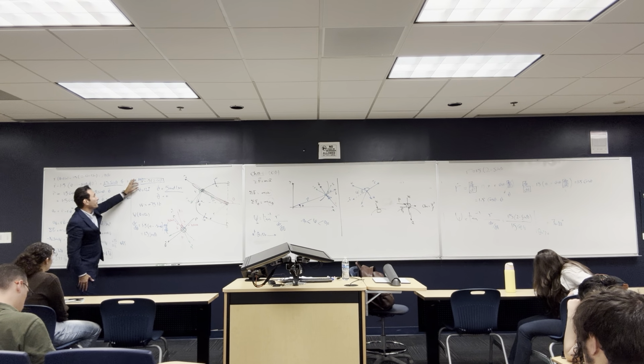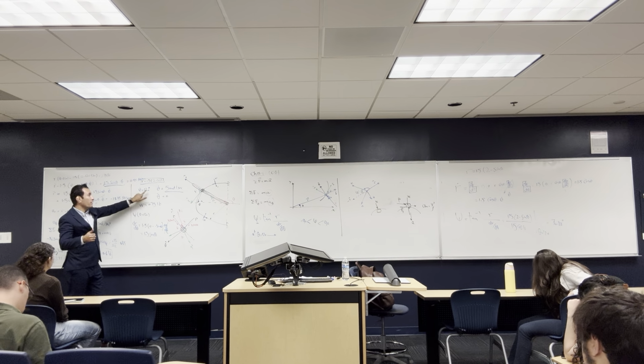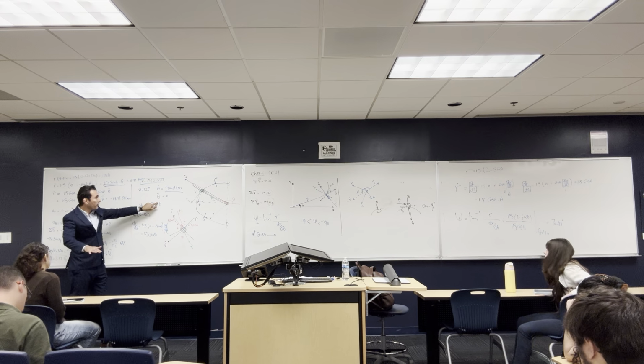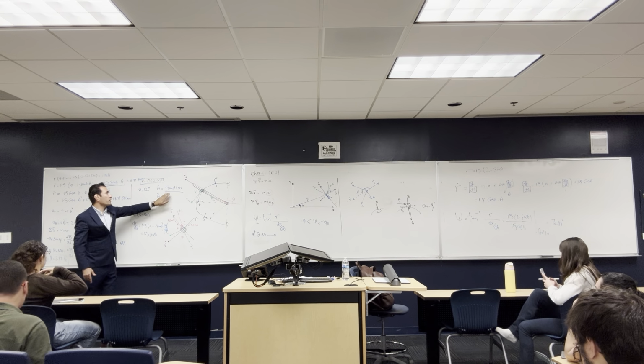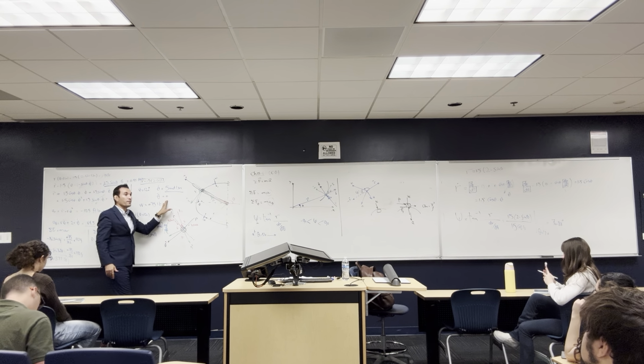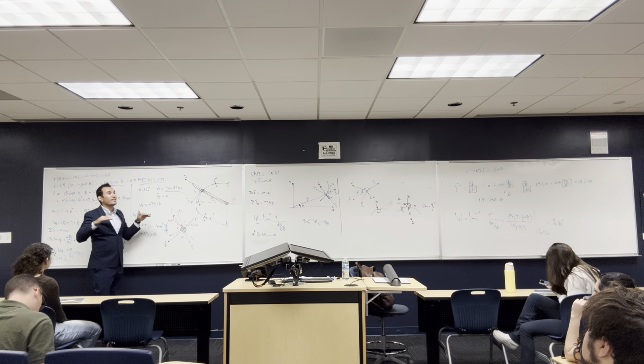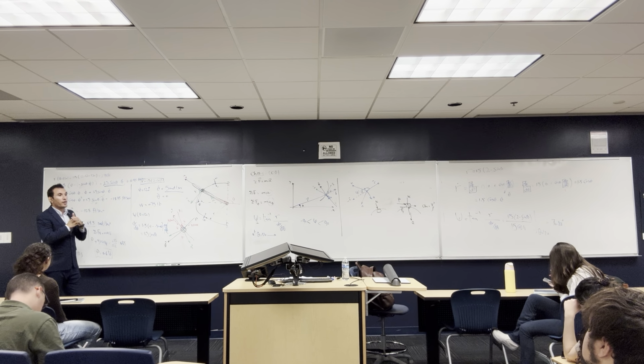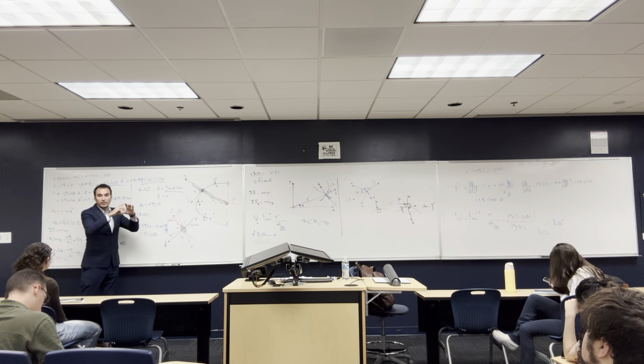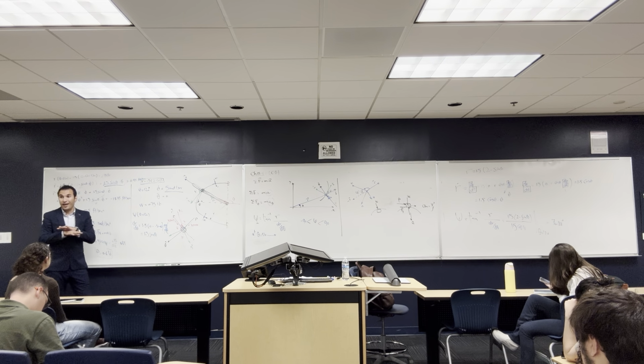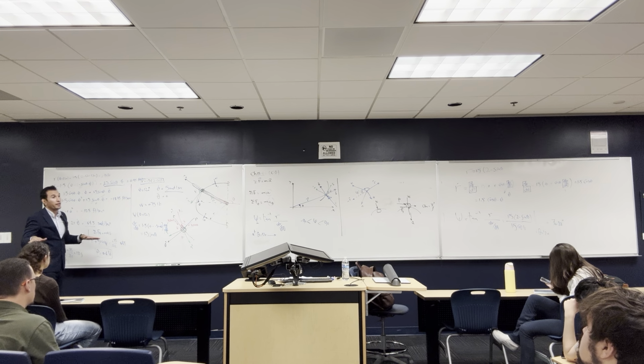I try to find the values of theta, theta dot, and theta double dot. I got them: 120 degrees, 5 radians per second, and it's constant velocity, so theta double dot is 0. I didn't do any equations or solve anything. All this came from understanding what is given in the text. I didn't differentiate anything.